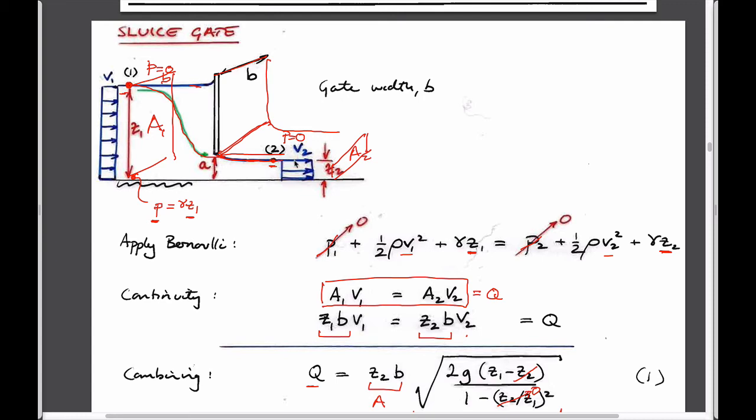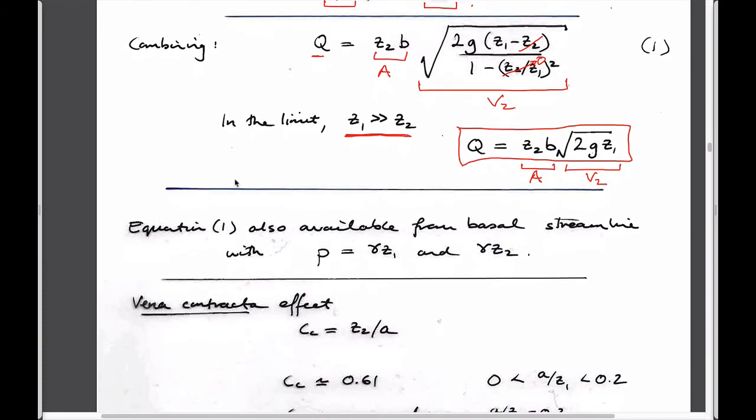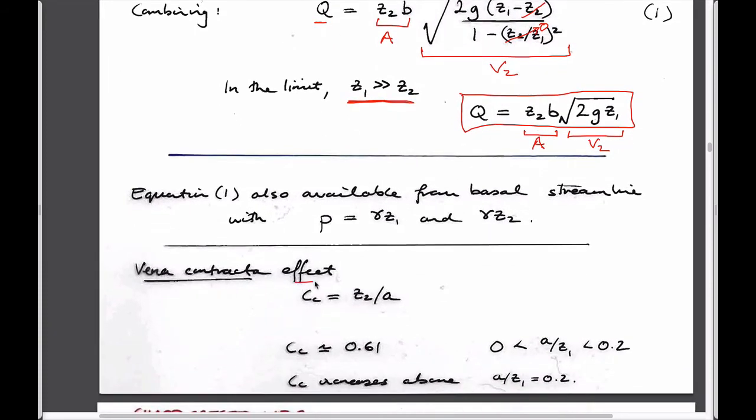And it turns out that the height of this downstream portion tends to be related to this magnitude here. And so that's useful if we know that for a variety of flow rates, the ratio of this height downstream, the depth of flow, relative to the orifice under the gate, is this. And it often is quite narrowly constrained to be some number, roughly 2/3.